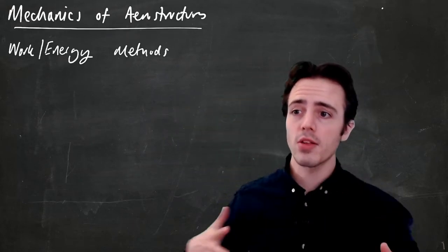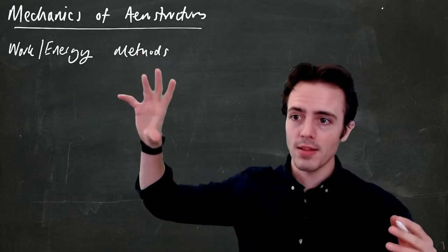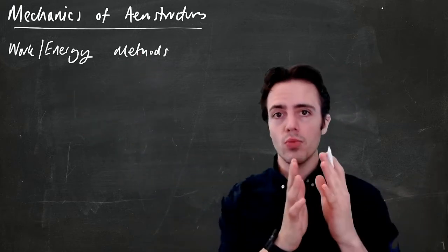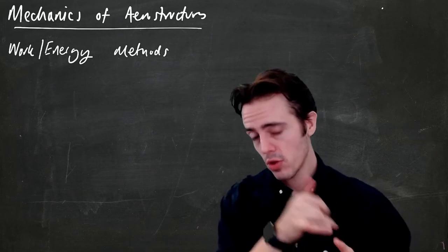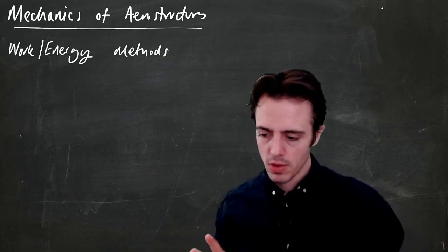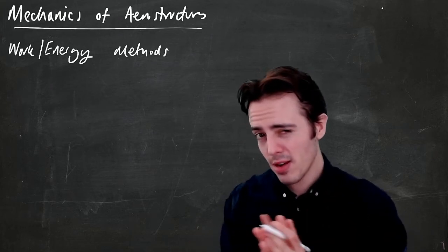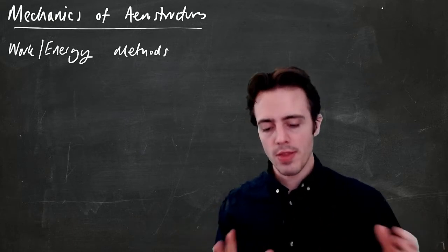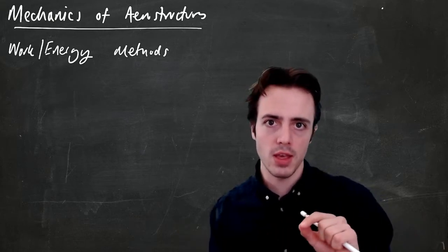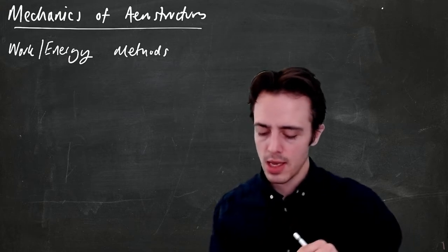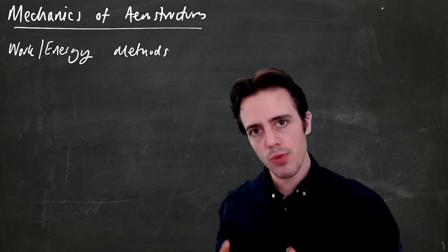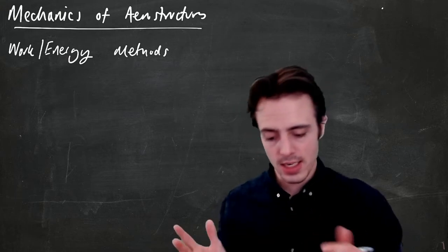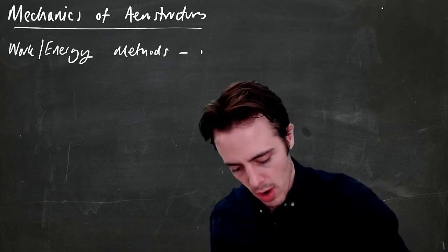Right, good afternoon everyone. So we're introducing work energy methods today. We've gone through what has been a bit of revision about the method of joints. We introduced the force method, and we're going to use the force method to determine both the reactions, the redundant reactions, and the redundant internal forces if we have a structure that's statically indeterminate. So we'll say work energy methods.